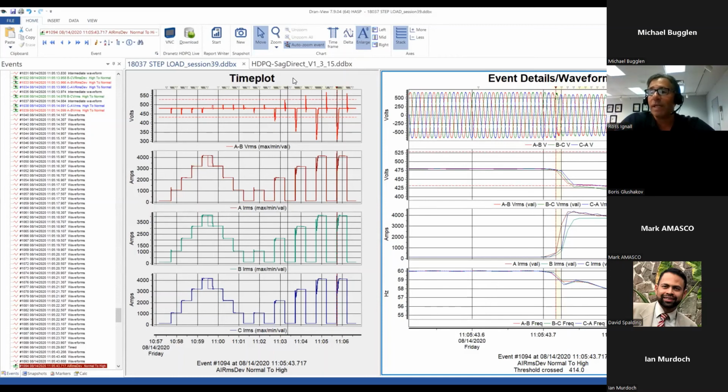And by transient, it means a change, not the high frequency transients that we're talking about here for power quality. What they'll do is step the load through load banks, usually to 25%, 50%, 75% to 100% of the current capacity on all three phases, and then back it down to 75, 50, 25, and then 0. Then they do impulse tests from 0 to 25, 0 to 50, 0 to 75%, and then 0 to 100% of the full load capacity.